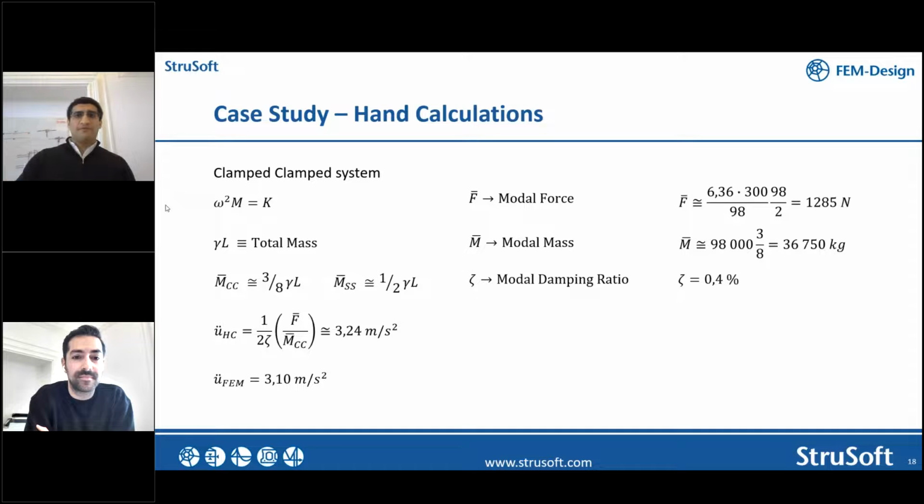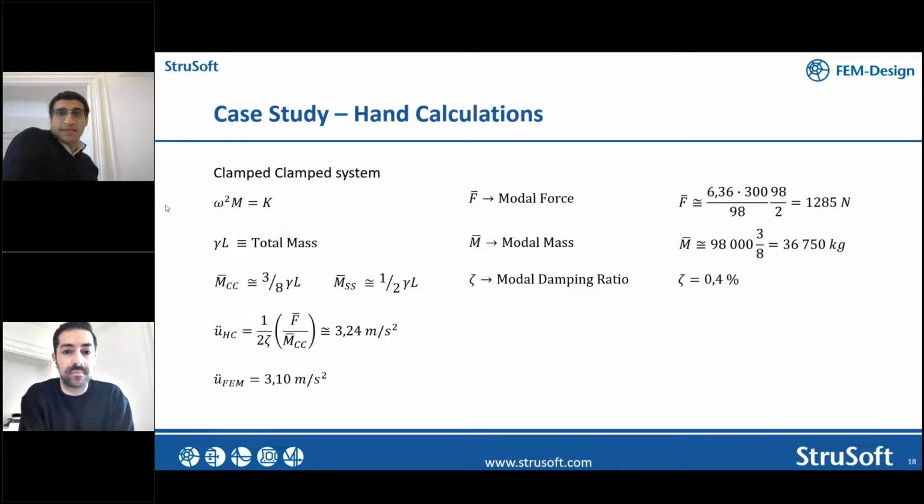So if you define the modal force using a sine shape, that's pretty much a simply supported beam, what you would find in the set of examples. That factor is going to be 2L/pi, and that's the factor you need to multiply the amplitude of your load by such that you will get the modal projection. So that would be your modal force applied.